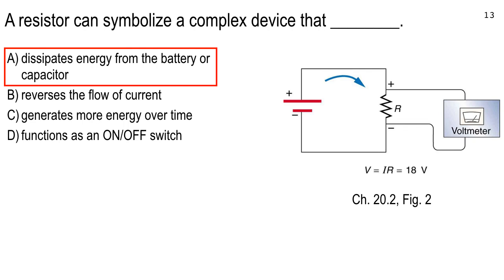Refrigerators, you ever notice that? The bottom of, or the side of a refrigerator, they have a fan in there, right? To cool off the cooling coils. They have a compressor that has to work, and it compresses the freon, and the freon goes through these coils, and they take warmth from the inside of the refrigerator to the coils.